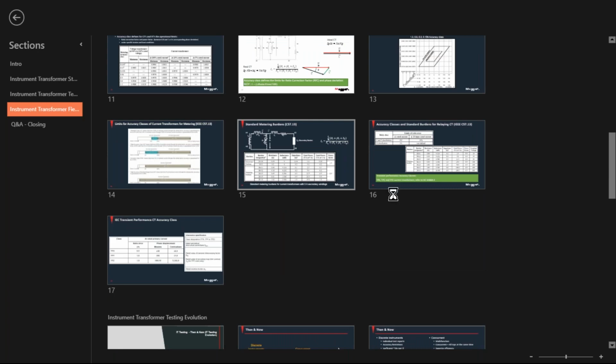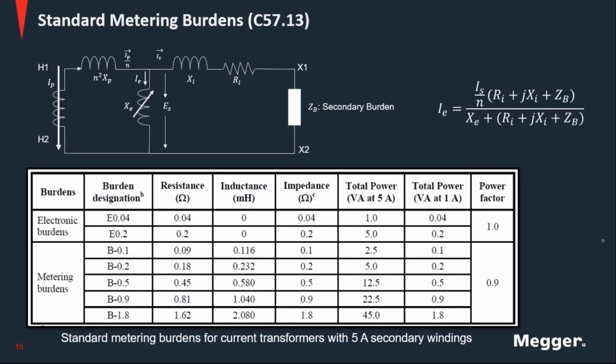It could be a change in the iron itself. Let's say there was a fault in the system. The fault drove the CT to saturation, and when the CT came back out, given that the voltage applied to the secondary of the CT during normal operation is so low, because at nominal current you will be talking about only a few volts applied to the secondary of the CT, there will be some amount of remnant flux in the transformer. That can increase the excitation current on the transformer.